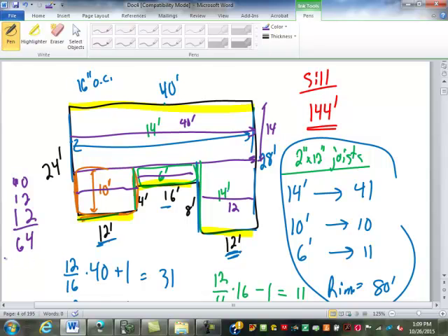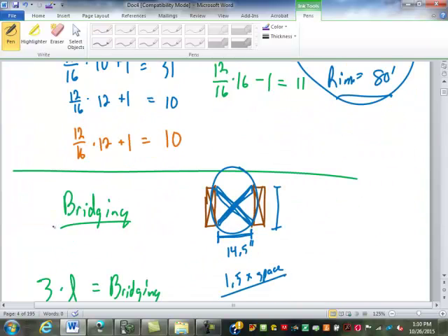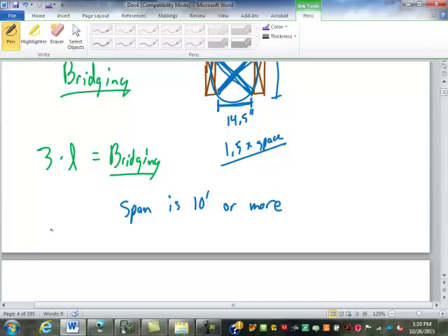Really, engineered joists don't need bridging. TGIs, yes, they do. Those have to be bridged if they span more than 10 feet. A lot of times for them, what they just do is a block, like the strong back style bridging, like I showed you. 15 and a half inch, you stick it up in there and you pull it down in between and nail through the rod. The problem with strong back bridging on a joist, well, let's do this here first.